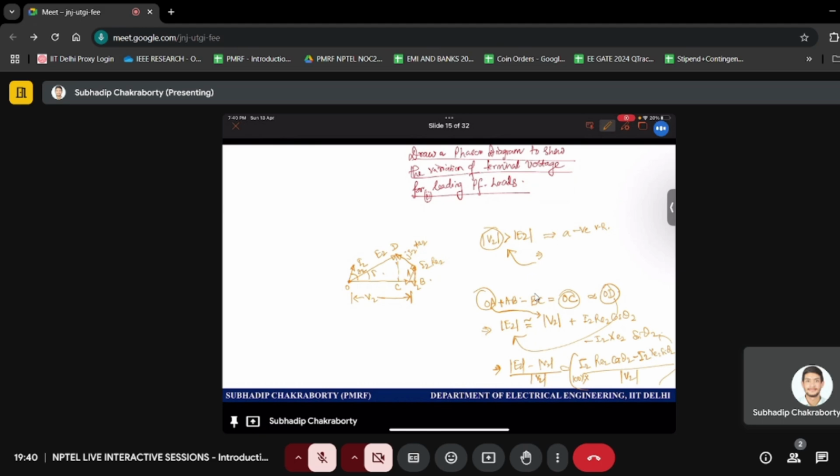So this is the formula where we see a negative sign indicating negative voltage regulation for leading power factor, and the negative sign just implies that V2 is greater than E2 for certain leading power factor operation. But you understand that zero voltage regulation is also possible. It is not possible for lagging power factor operation, but it is possible for leading power factor operation. And just by equating it to 0, you can calculate the power factor.